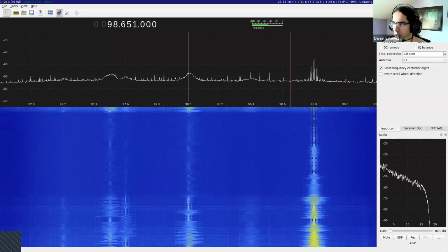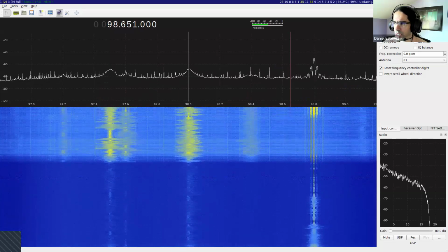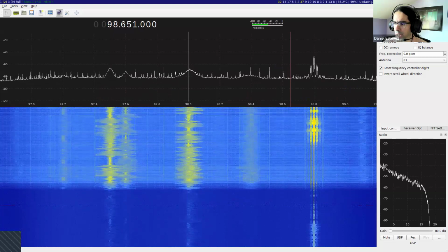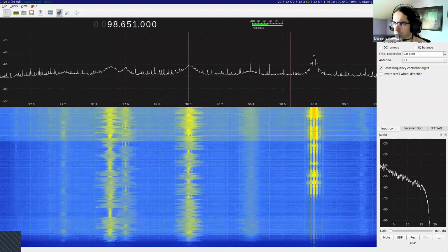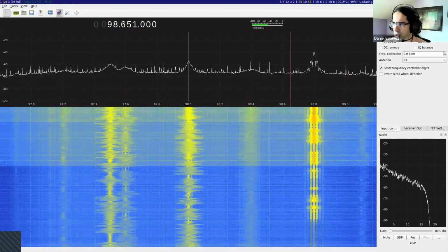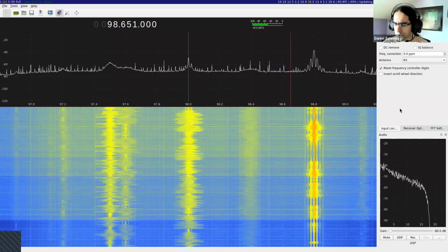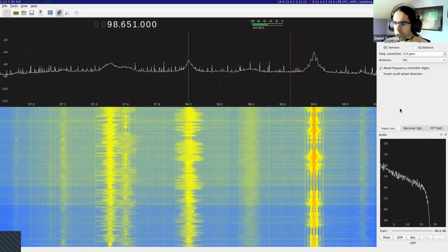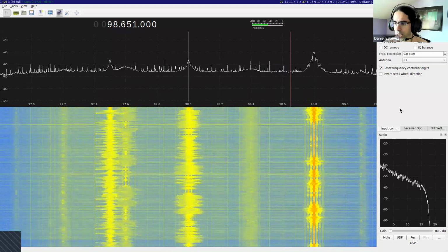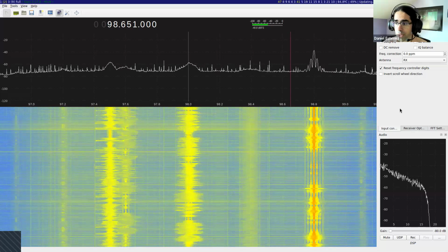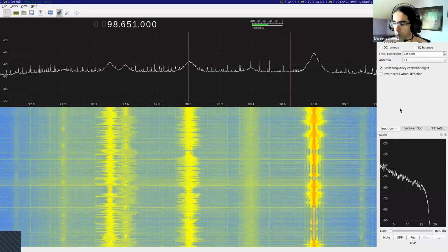So the conclusion is, by doing this kind of study, the sweet point is 20 dB, 30 dB, something around that. It's never a critical value. You just need to set it to something reasonable. So I think I'm going to go with 30. That's one method. Basically, you have a signal and you figure out how signal to noise ratio changes as you change gain. There's another method which is useful if you don't have any signals to use.